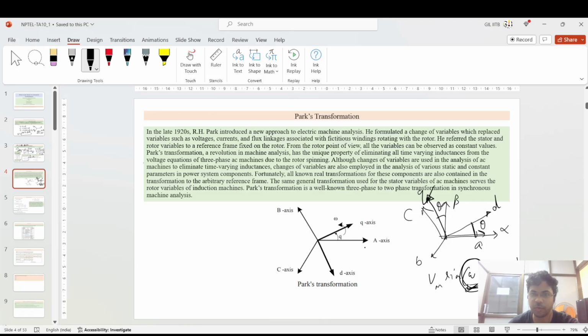For the definition of this rotating frame of alpha beta, you use the Park transformation. You converted initially from ABC to alpha beta naught, then you can convert to the DQ naught frame, and this DQ naught frame actually needs this omega t term, not the alpha beta naught.